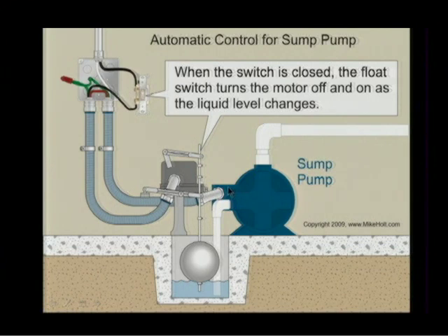Eric, you said that we could put a flow switch in this motor, right? With a flow switch, we could then determine whether or not the motor is actually pumping any fluids. And if the switch is closed, and the overloads remain closed, and if the contacts for the flow switch are closed, then the motor should be running. Then we need to make sure we have liquids. And if we don't have liquids, then we can have something else, through some other computer control, saying, well, then turn off the motor, if we wanted to protect the motor against a lack of movement.